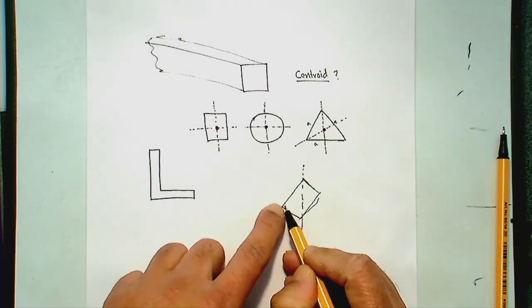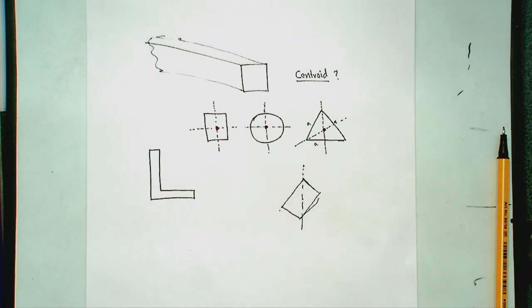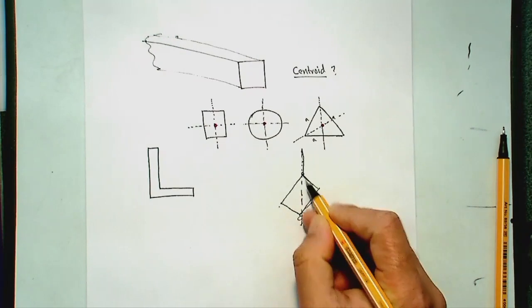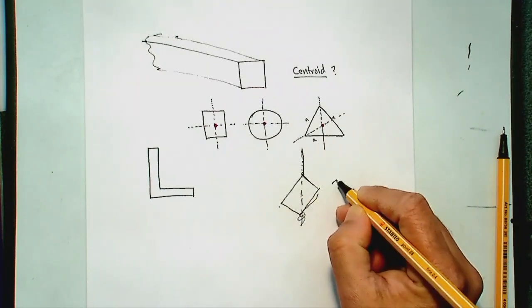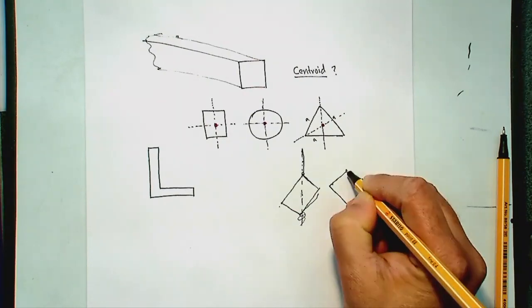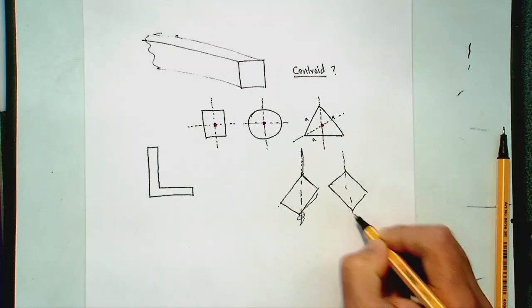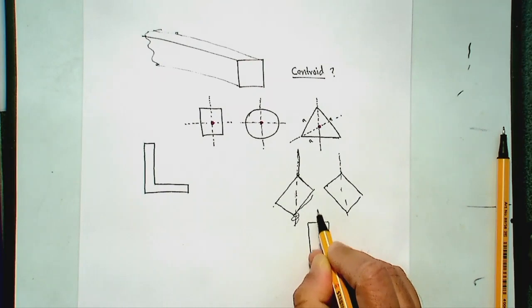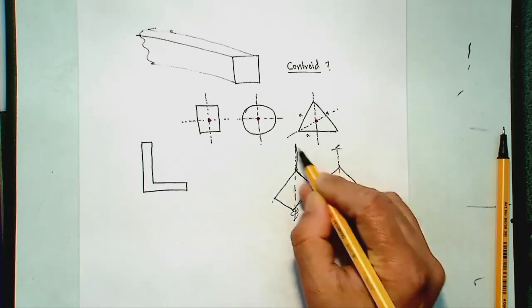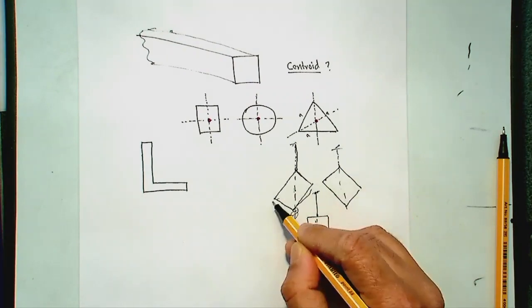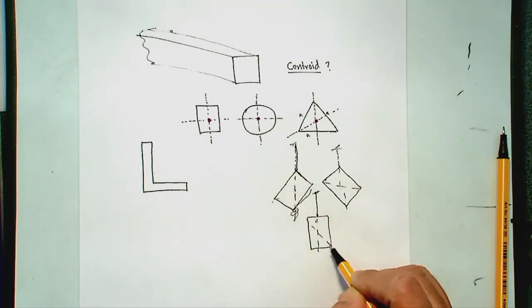Okay? Then you attach another point and hang it that way. And then if you extend your thread, so this is your thread, and then you put it into another corner, attach it with a thread, then it will be in this way. Then you attach a thread somewhere through the middle and hold it in this way. And then if you draw those lines on the piece of paper that you had, that would give you the axis of symmetry.